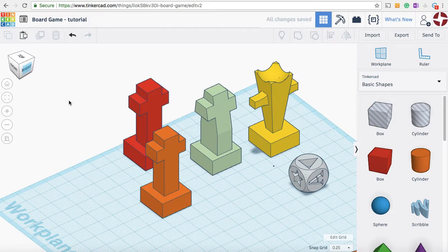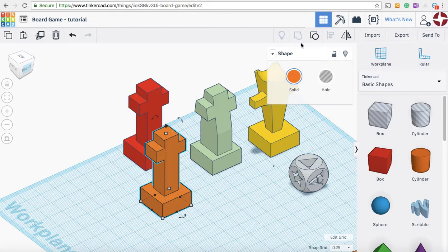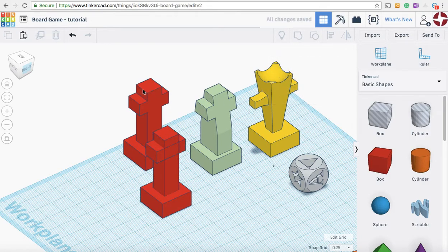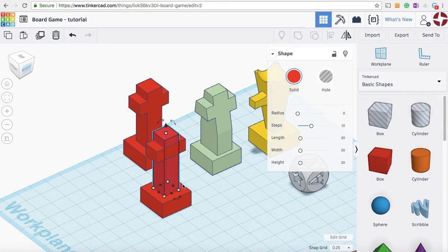Okay, so what I've noticed different here is this one's a lot fatter through this center column there. It's angled there as well. We'll get to that later. First, I want to increase that distance there. So this is all one group, so remember, I'm going to ungroup. Doesn't do anything to the other one I copied it from. Just ungroups this one. Okay, so this one is 20 millimeters there, so I'm going to select the middle one, and it looks like it's a bit less, so I might call that 17 maybe. There we go, that's not too bad.